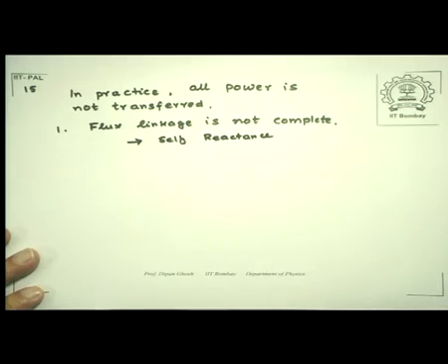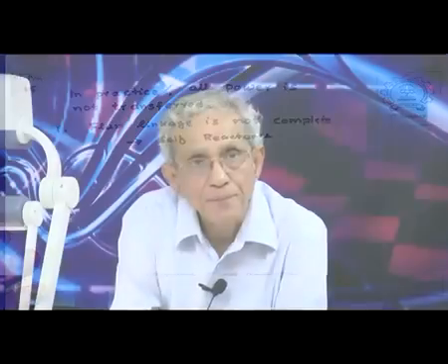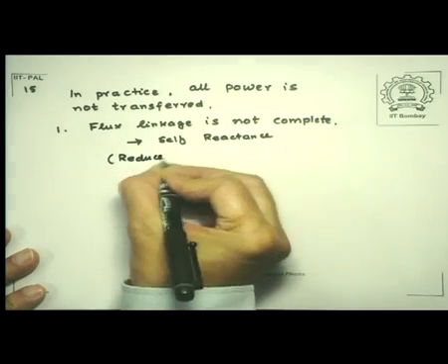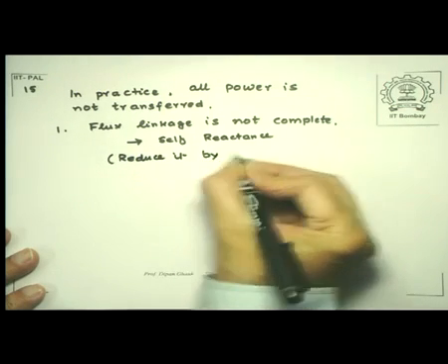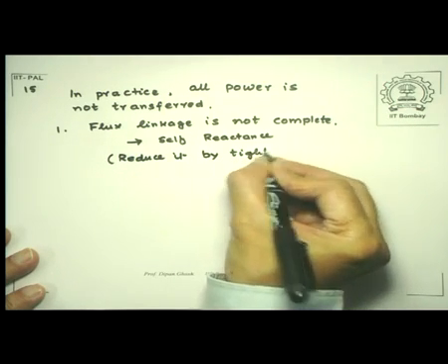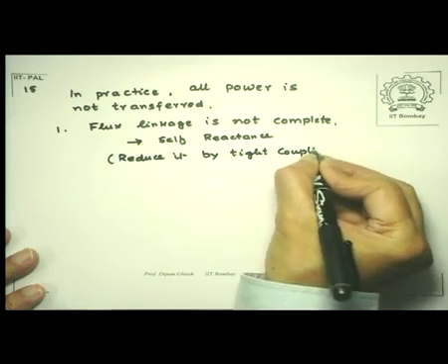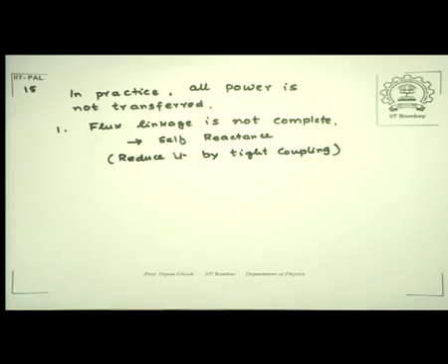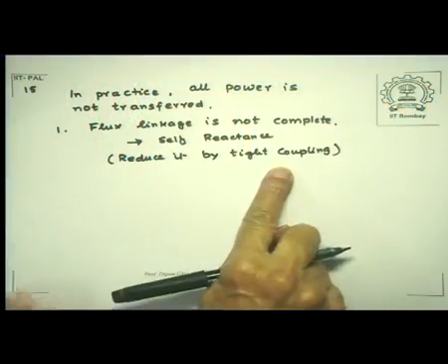I can reduce the effect by tight coupling. What is done in tight coupling is to wind the turns of the secondary on the same core on which the primary windings are put. So that would make the coupling somewhat tight.